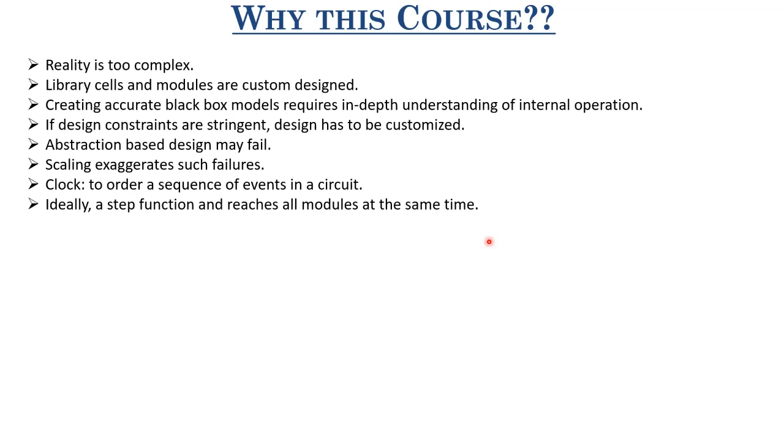Because, as I told, these digital circuits are sampling some voltage, right? So if the sampling instances are different, maybe during that time that voltage may have changed. This may lead to erroneous sampling of data in the registers, as we shall see when we discuss the modules on sequential circuits. But for the time being, just understand that this clock is pretty sensitive, and each of the modules should receive the clock at the same time.